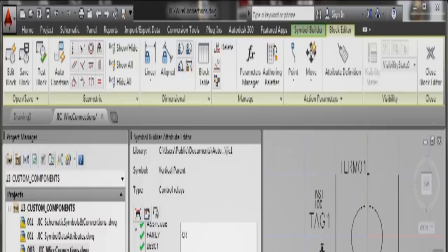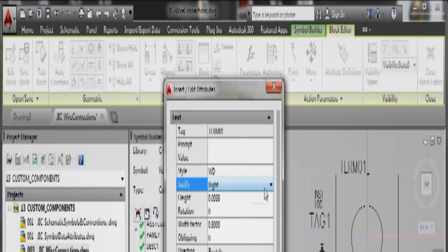What we need to do is make sure their properties are correct. So there's the top one. I'm going to click here and go to properties. I want it to justify to the right, going away from the actual block itself like that. And you've got rotation, for example. I can rotate that through 90 degrees if I wish. If I do that and press tab now, that'll update and it'll rotate through 90 degrees. I don't have to have it there. I can leave it at 0 if I want to. It really doesn't matter, because basically what I'm setting here is it's a top connector anyway.